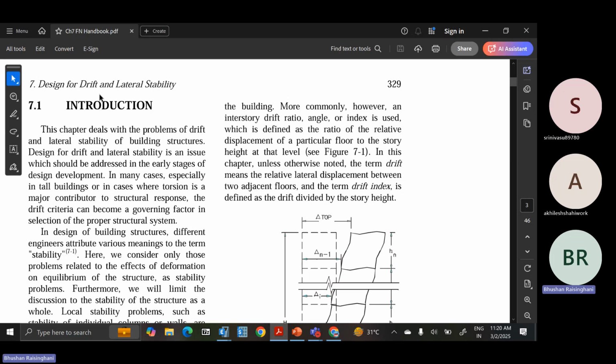So due to any lateral load after application of the critical axial load, the column will become totally unstable. So there is a bifurcation load. We call it PCR. So PCR is equal to the bifurcation point, wherein when any lateral force is applied, or any increase in the axial load also, there will be a lateral displacement, and that will lead to an unstable condition of the column.